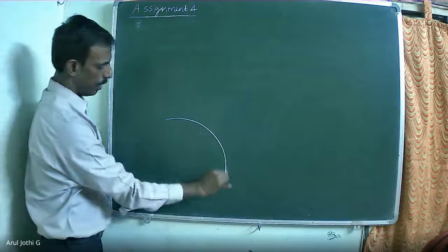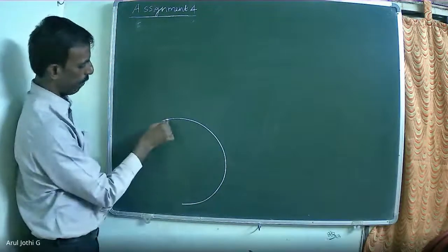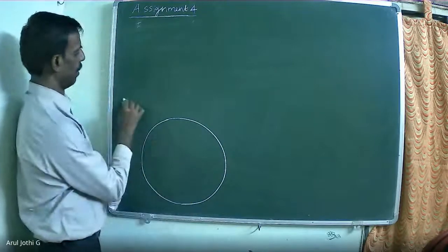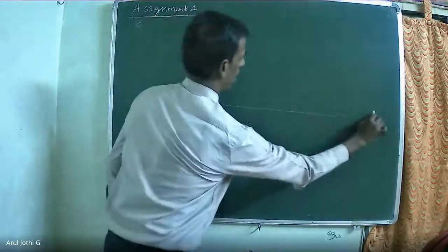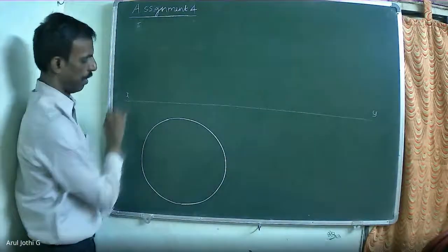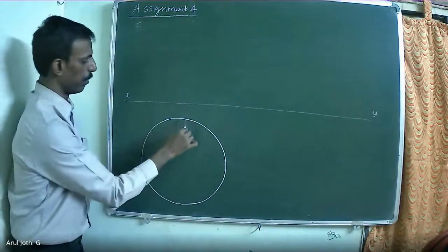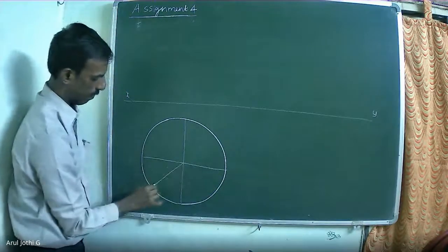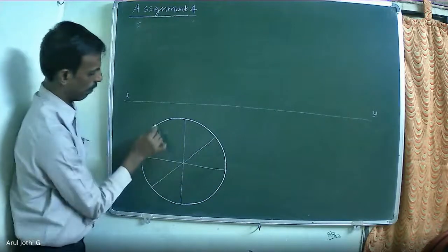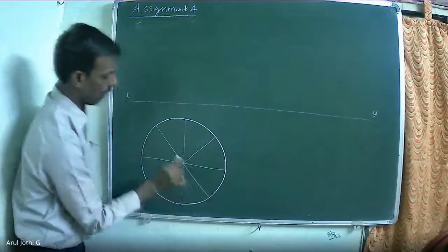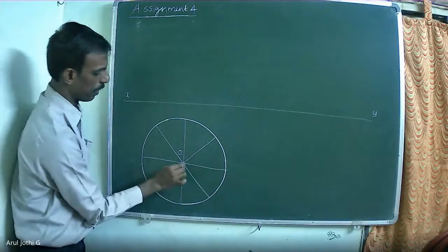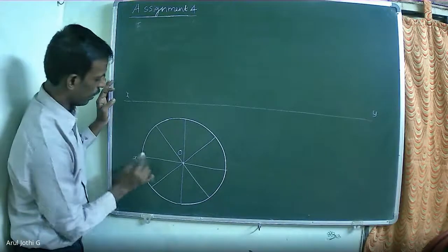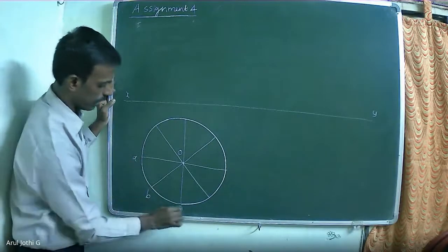So draw the circle with the base diameter 50 mm. Now divide the circle into 8 equal parts. The center point will be the apex point. This intersection point will be apex point O. For the base circle generators, we are going to give the notations.